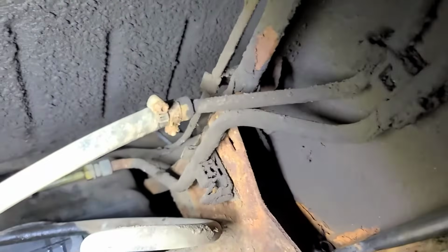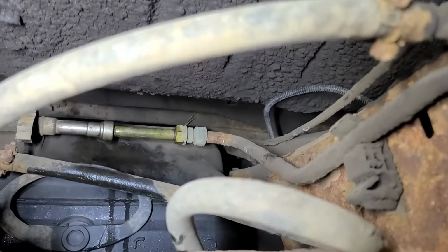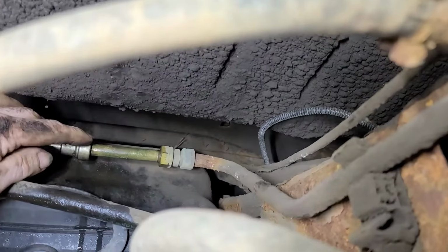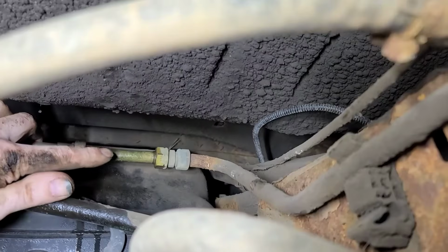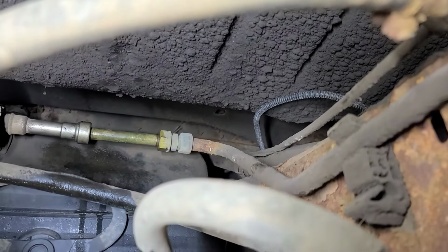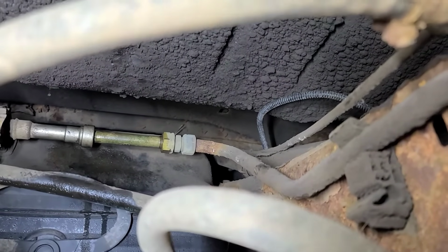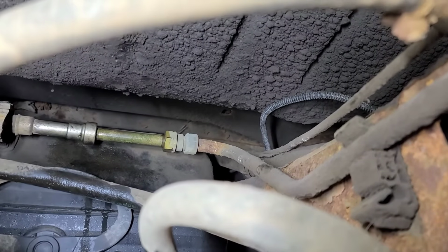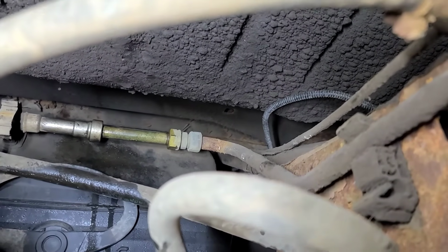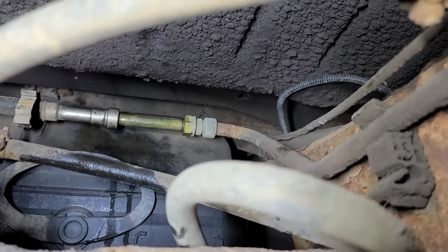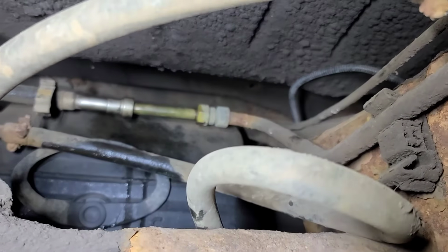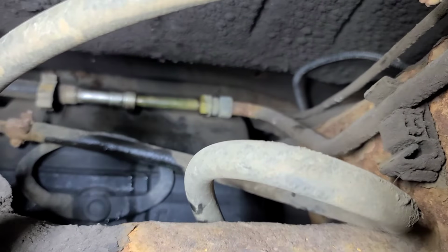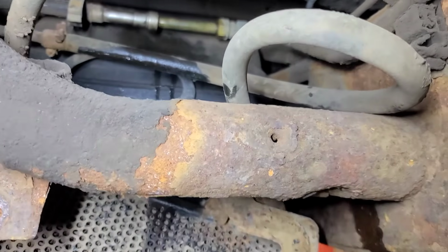So I dropped the cooler off the frame, and I wondered why that line was relatively clean looking. So it's been repaired. You can see there's a section aligned put in with a brass union. I've got smoke under pressure on it right now, and I'm trying to release this fitting here, and it won't release. Anyways, I'm going to try and get that off and put a piece of clear hose in there and start it up to see if I got bubbles coming from the tank.